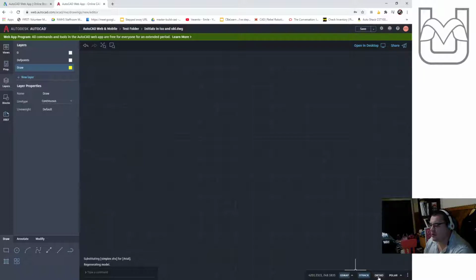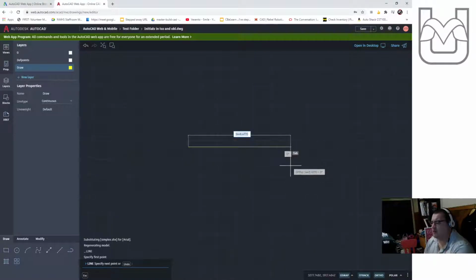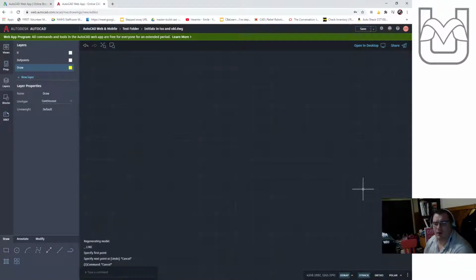If you end up checking off orthographic here, I just want to click on this because somebody's going to do this in the course of this assignment. If you click off on orthographic, it's only going to allow you to draw lines vertically and horizontally. Please don't click off the orthographic button.